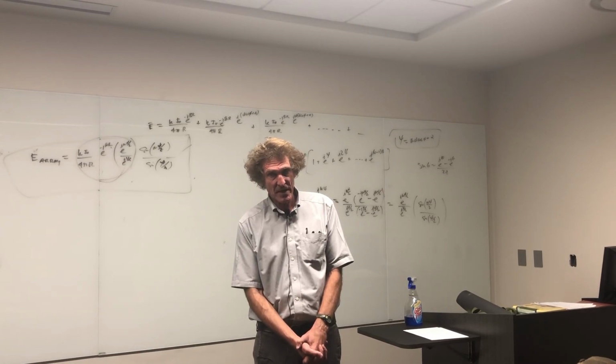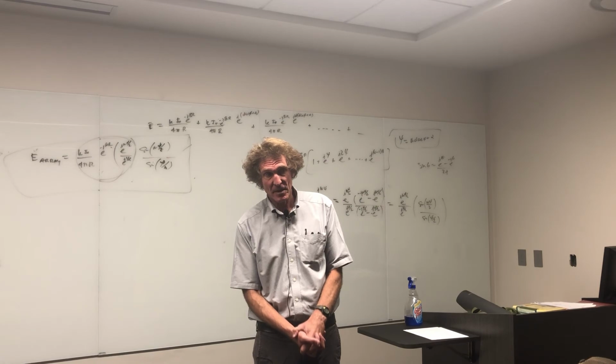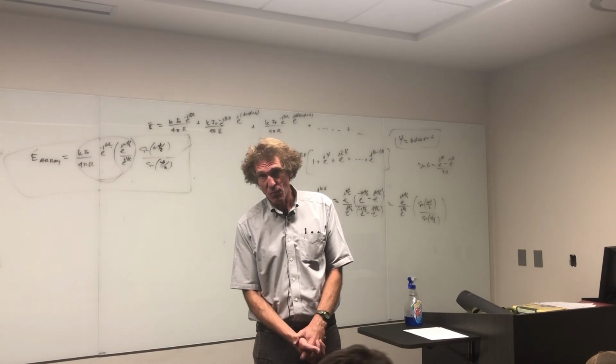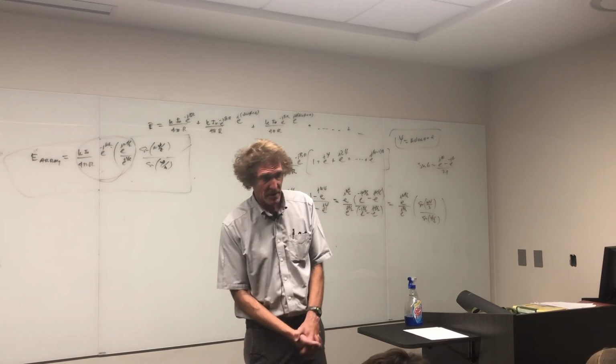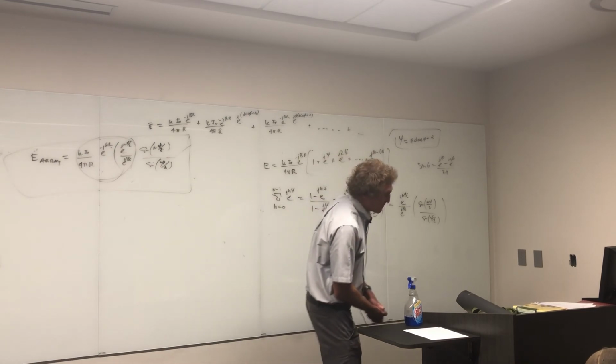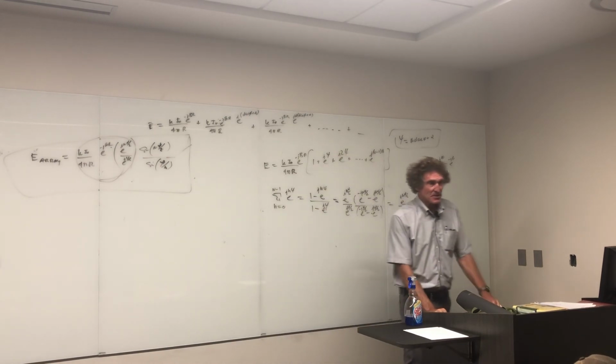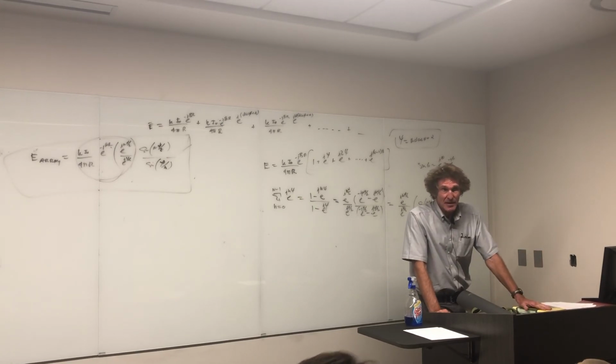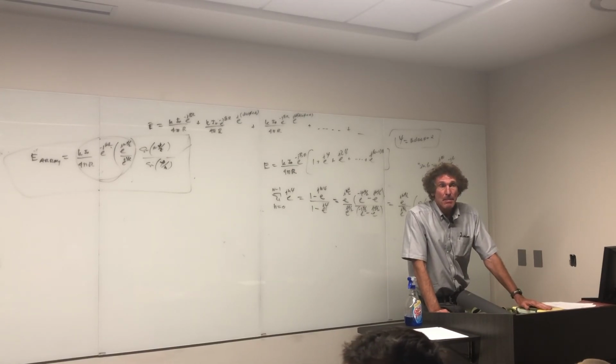Remember, there's always that factor of 1 minus FC over F squared for waveguides, and that FC is the cutoff frequency of the mode you're talking about. For instance, the 1,0 mode is the lowest order mode that allows propagation. You have to be above that for propagation. Other than that, I'll answer any questions. There's no formula sheet except I would give you the formulas for oblique.